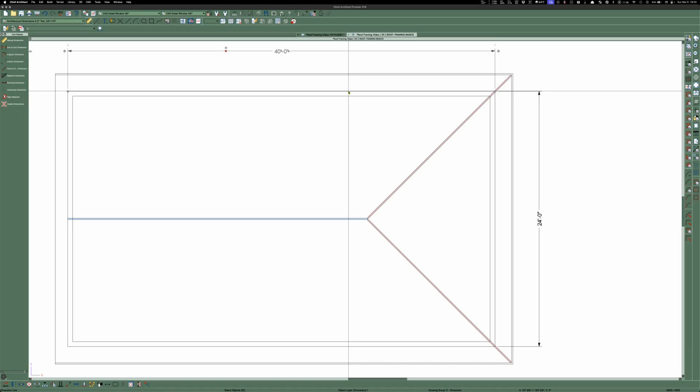Or if you're like Tim, he'll just get out a chainsaw and have everything all bundled up, and he'll just one cut 50 rafters. Well, maybe not that many, but quite a few. Yeah, he's pretty impressive. I don't trust myself. I would get off, and then I'd have rafter headaches. But yeah, you pull down to here, you make a mark, and you apply your tail pattern, you trace out the rest of it. And that's what you do. And it's not hard. It's not bad.